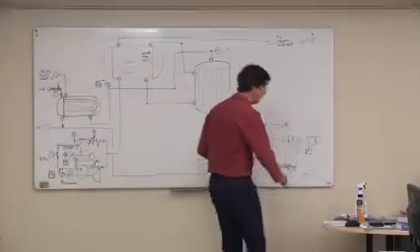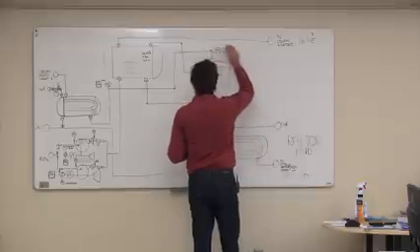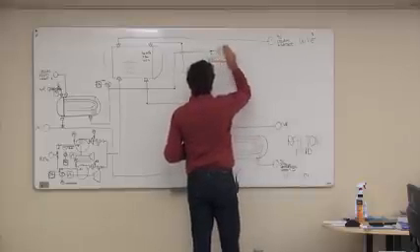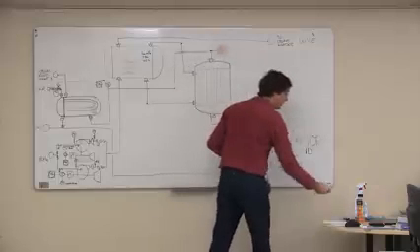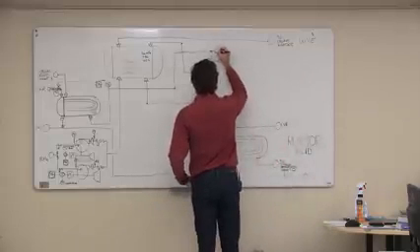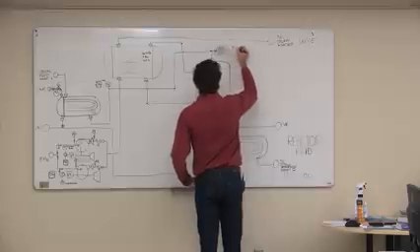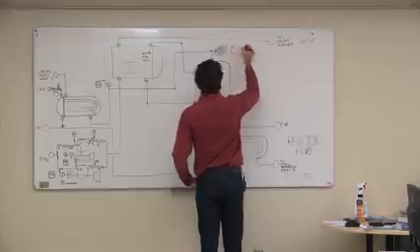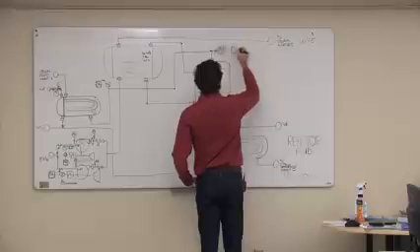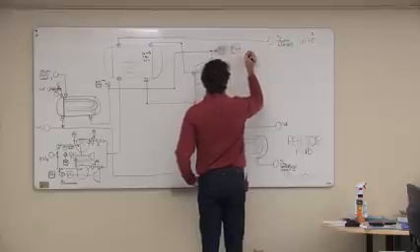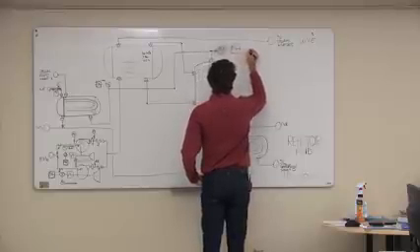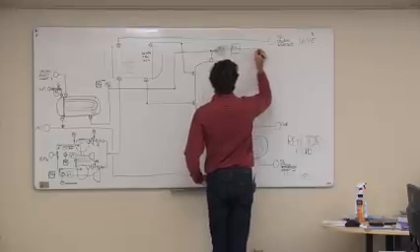The next thing we probably want to know is what the pressure is into the reactor, because pressure is going to be an important factor in the molecular weight. So let's add a pressure indicating transmitter, put that into a pressure indicating controller, and somewhere that pressure indicating controller needs to control something.